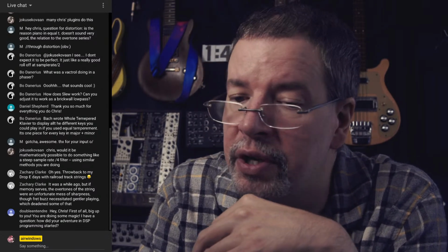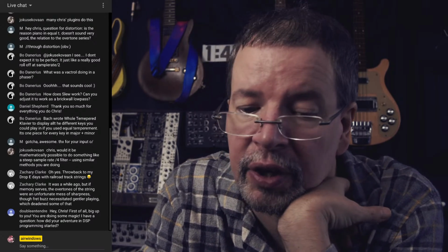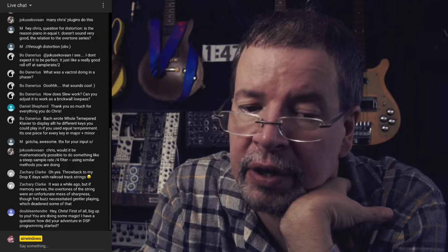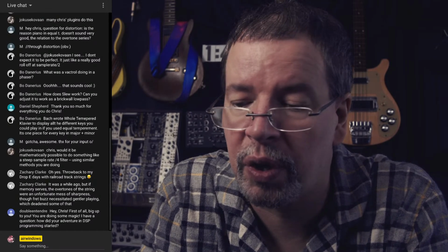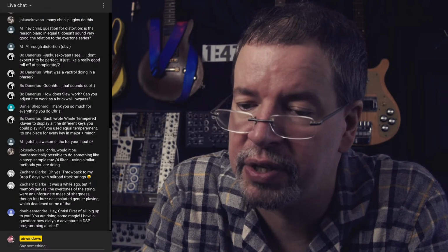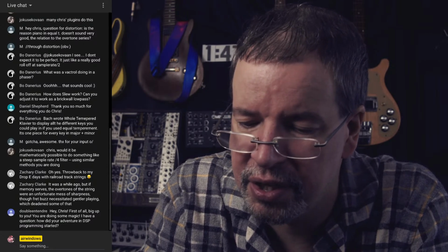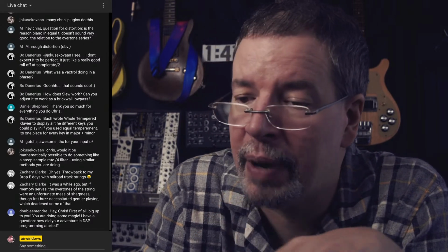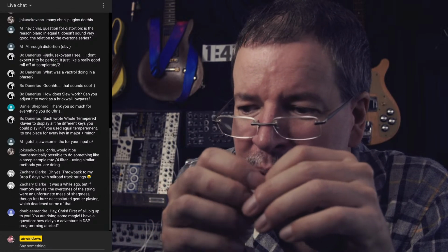And you can use them as a sort of fuzzy 2B style amp with a very characteristic distortion. And I ended up building all kinds of circuits based on that. I ended up building a circuit where every single stage of the 4049 was wired up and distorting every other stage. 6 stages of distortion, all with very small capacitors wiring them together into this little jewel of a chip. And basically it just screamed.